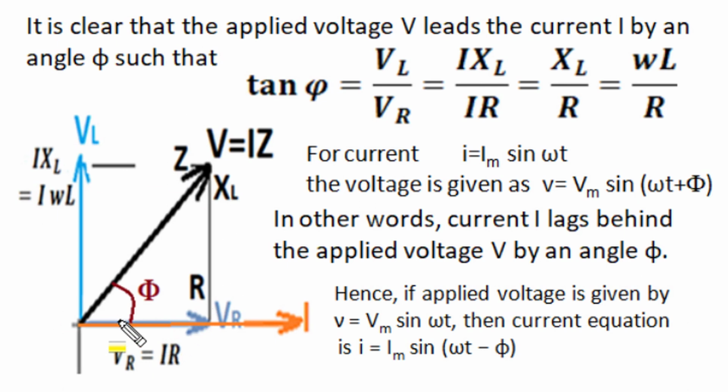The complete phasor diagram or current or voltage relationship can be obtained by study of impedance triangle. For impedance triangle we know that R has no imaginary part, it is entirely on horizontal line, it is R angle 0 or R plus j0. Similarly, inductive reactance won't have any real part, it is plus j type quantity, or it is XL e raised to power j90 on positive vertical line. So this is position of R vector, this is position of XL vector, and their summation is Z vector.